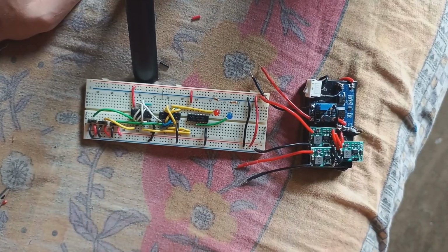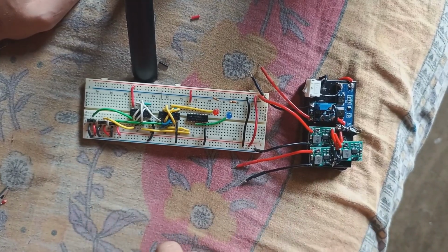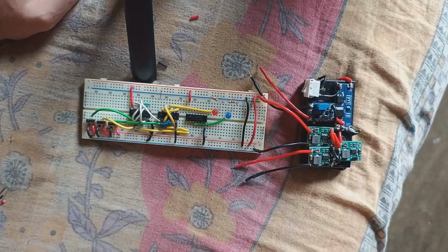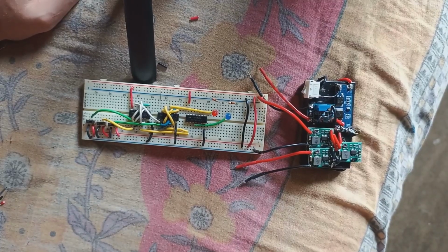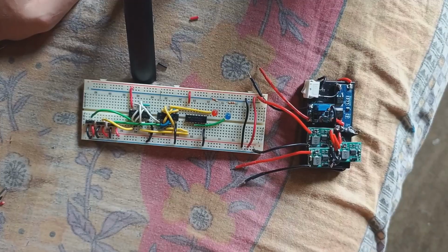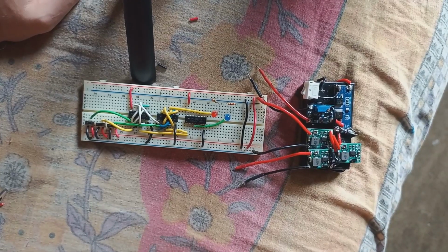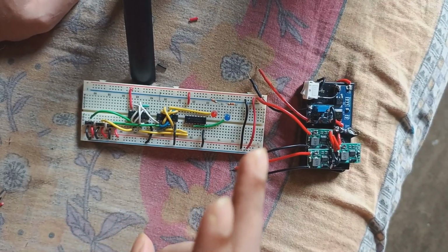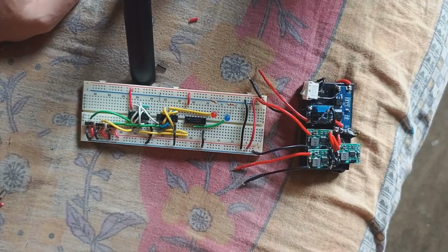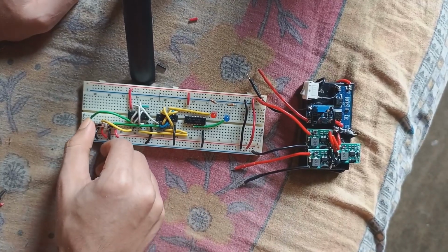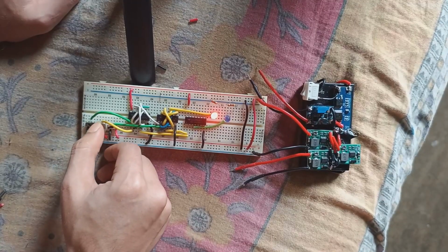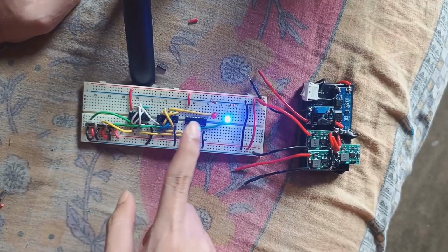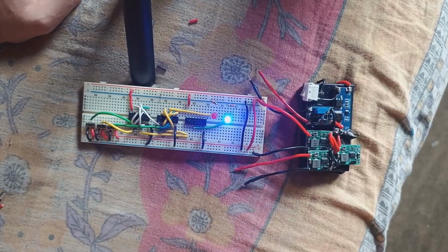Now let's get the combination of 1, 1 and 0. If I sum 1, 1 and 0, the sum will be 0 and the carry will be 1. That's how binary addition works. For that I have to give 1 to any two variables and 0 to the other. First turn A on, so A is 1, B is 1. When A is 1 and B is 1, sum is 0, carry is 1, which is desired.